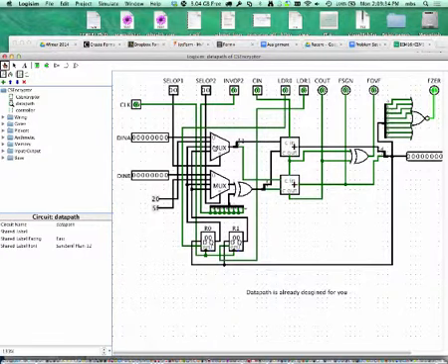The 4 inputs for operand 1 are either coming from an input called D in A, which is one of the 8-bit inputs into the data path. It can also come from a constant value, hex 20, and hex 20 is actually the ASCII code for the first printable letter. It's chosen carefully for that. And then the other two input choices for operand 1 are two registers I have provided, R0 and R1, where you can remember things.